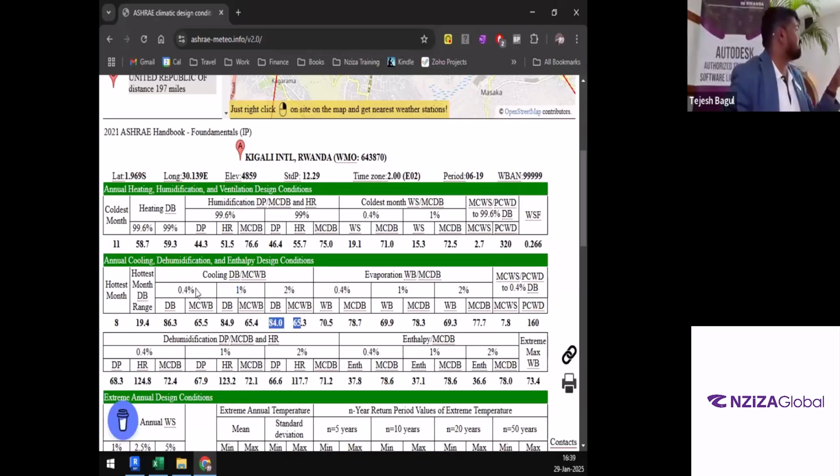As I indicated, in case there are special conditions that a senior engineer is asking you to use, the reason being, as you see, these numbers drop down when you take a bigger chunk out of the year. The reason being your average is coming down. Over here, this is the worst case scenario that we are working with. If we have our ACs designed to this temperature, it is basically 2 degrees Fahrenheit lower as compared to what we have for 0.4% over here. So basically we are trying to go with the worst case scenario, how hot it can get for a small period.